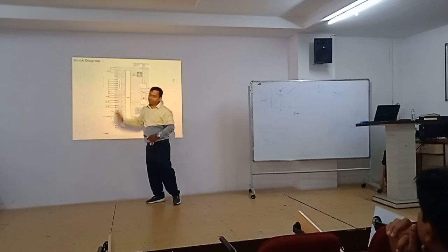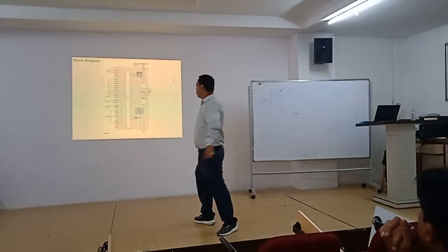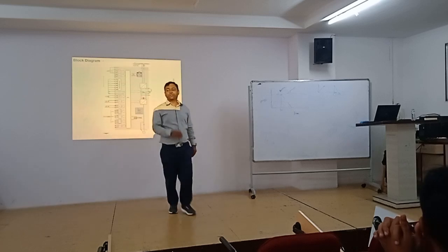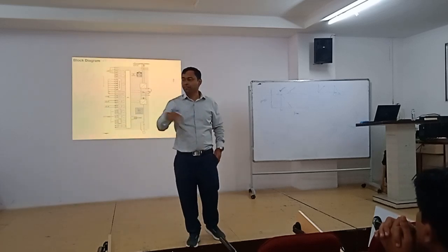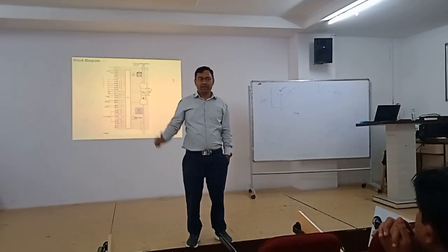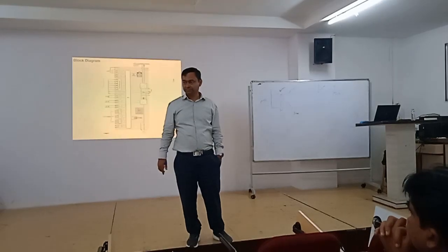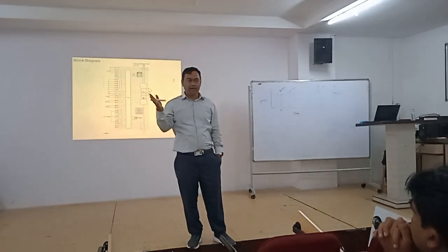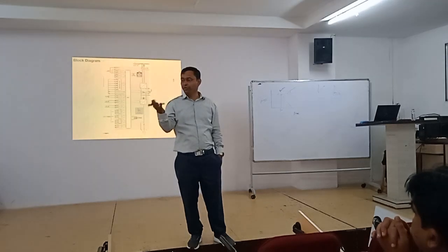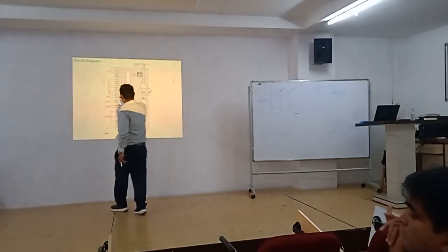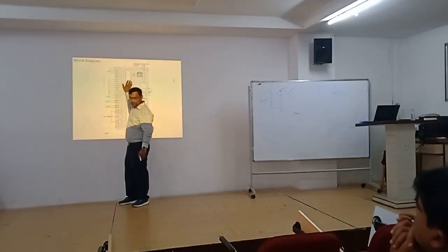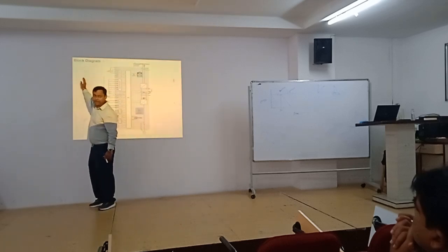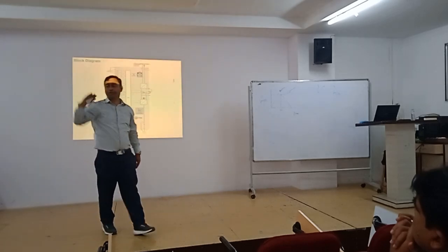And along with this, the main thing is here. You have so many digital inputs. So digital inputs are for what purpose? To start the motor, to stop the motor. From where can you start and stop the motor? From manual you can do. Second is remote, you also can do. You can connect the start and stop input of the VFD to the PLC output, and connect the PLC to the SCADA and operate the motor remotely. So remotely also you can make the motor on.